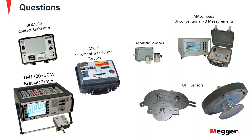Does the MRCT test set demagnetize the CTs on its own? Well, yes, the MRCT, when you look at the software, there is a feature called run all tests, where you just click and say, okay, I want to do everything possible on a CT, and certainly after the DC-based tests, the unit will automatically go to a demagnetization routine before performing ratio saturation of the AC-based measurements.